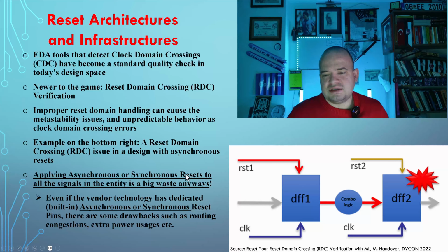For instance, in this design, maybe asynchronous resets are preferred because the technology has built-in asynchronous resets. If you have those built-in pins in your flip-flops, then of course you are saving lots of resources because they are there in that ASIC design. Those reset pins are provided.